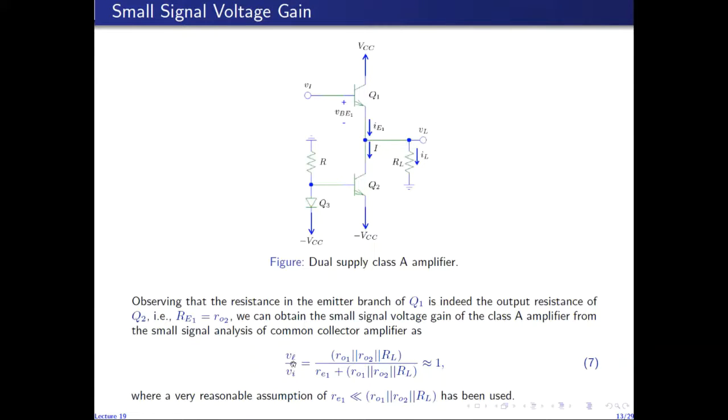Here, V subscript small l is actually the AC component of this V subscript capital L. Please notice that this convention of the lowercase letter and uppercase subscript represents the total quantity. Similarly, this represents the total current. But under quiescent conditions, that is, when there is no signal, under DC conditions, the DC load voltage and the DC load current are constrained to be 0.